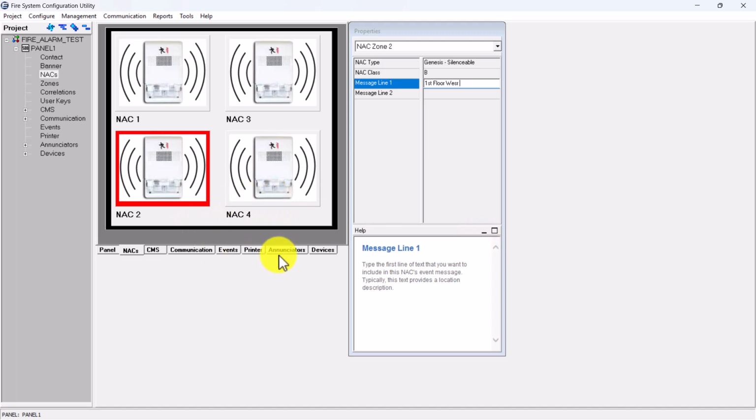And over here, down at the bottom on the output side, we want to activate. I don't want to activate the relay sounders. I don't care about that. And I don't care about modules. This is just a general alarm. So I want to activate all of the DAC circuits only.